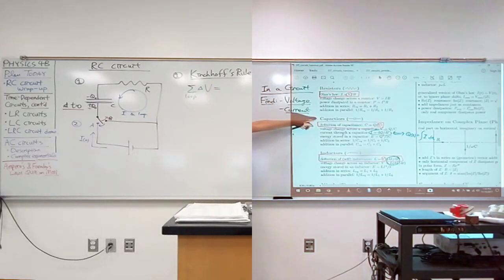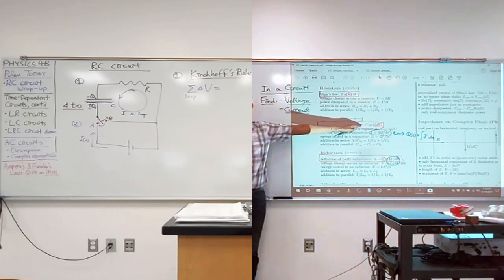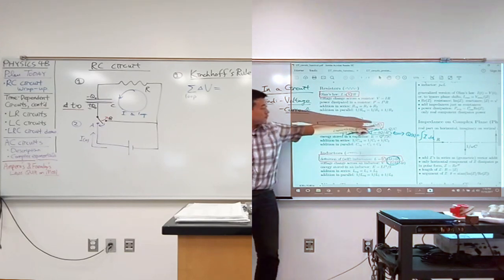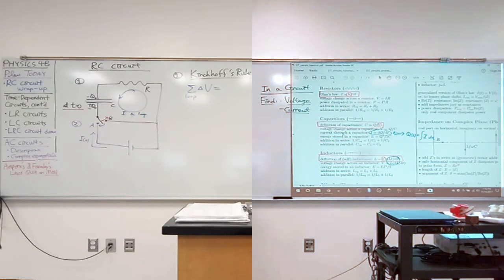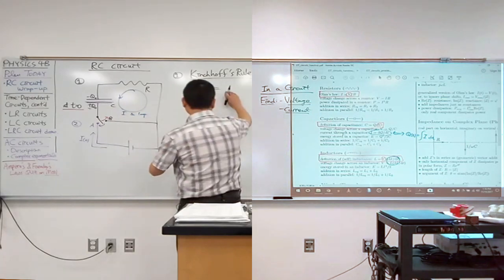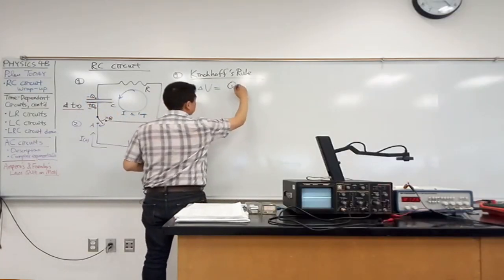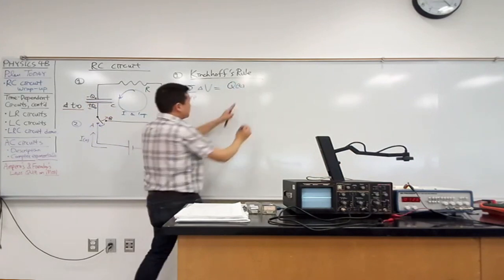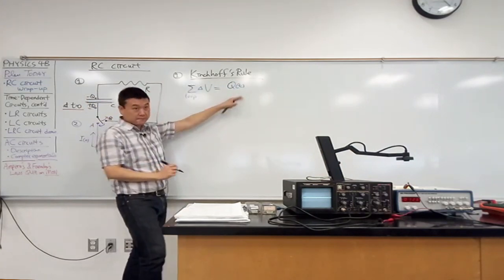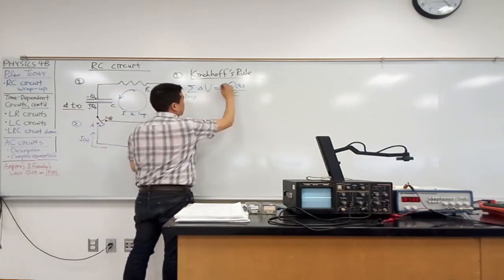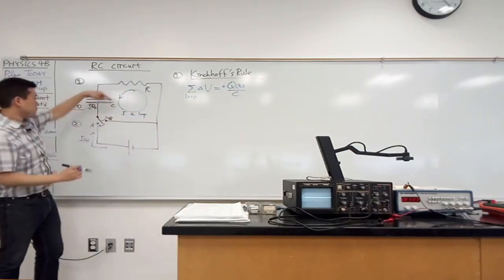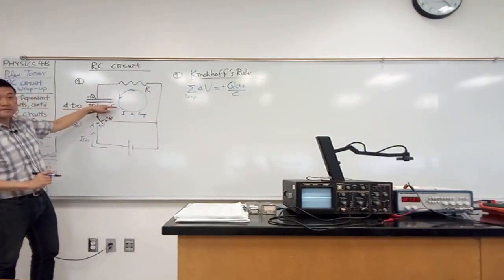I'm dealing with the capacitor. This is the definition of capacitance. Anytime you're dealing with a capacitor, if you're not using this, you're probably doing something wrong. So, yeah, V is Q over C. Do that quick algebra. So the voltage here is the amount of charge on the capacitor, Q, and I'm going to write Q as a function of time over C, and plus because I chose my direction so that I'll get a voltage rise.